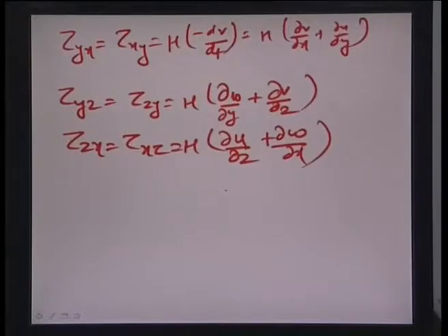And there are some other approximations that we need to make here, which come from thermodynamic pressure, the relationship between the thermodynamic pressure, the stress components, be it shear or principal stress, and the velocity. All these three are linked together, and I am not going to actually derive these pressure stress equations separately. It is an altogether separate topic, but I am going to assume the approximations made in terms of relationships between the different stresses and the pressure, and then put this back into the equation in question and figure out what the final form of the Navier-Stokes momentum equations, the conservation of momentum equations, would look like.